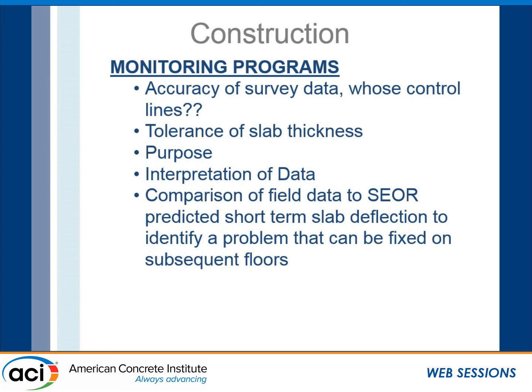And comparison of the field data to the structural engineer's predicted short-term slab deflection is very much a good thing to do. So if there is an issue, we can make adjustments as we continue up the building. Like I said previously, if you're doing a three-story building, there really isn't much opportunity to do this. But if you're doing a 40 or 50-plus story building, we're getting data continuously. We're submitting that to the design team, and we can make adjustments.